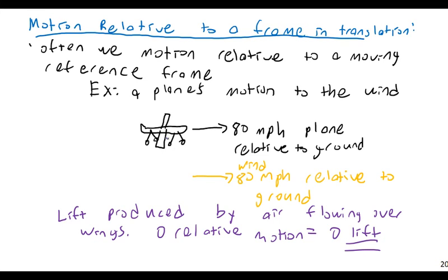Now, hopefully, the pilot is a skilled pilot, and the plane is built well enough that what you would do in this case is turn the plane as you're falling. You need some lift over your wings, so you turn again into the wind to give yourself additional lift. This is also why, depending on wind, it can be more difficult or easier to take off from an airfield. Again, to get lift, you need to have motion relative to the wing.